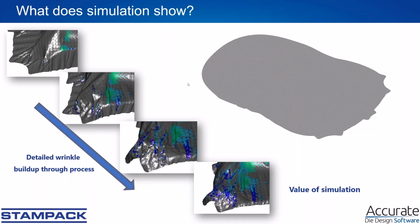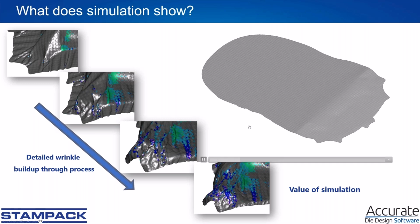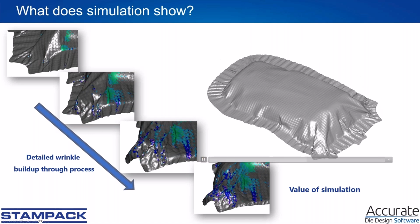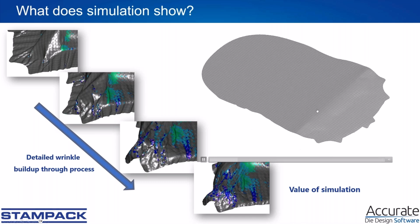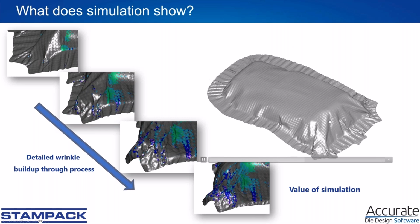What you can also see in Stampack is how the wrinkles appear during the process. So we have here an embossed sheet. So that is what people use to make heat shields. And here you see in Stampack we simulate including the embosses. And during the process you see very well how the wrinkles appear. And then in this kind of process, wrinkles are allowed, maybe in some other processes not, but they are predicted by simulation, and then you can judge whether you like the wrinkles or not. So in this case, it's allowed, but maybe in others not.